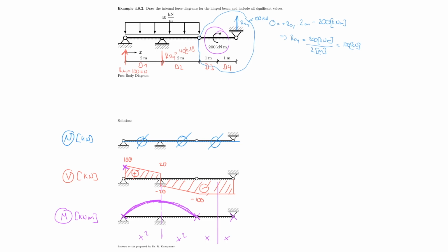So I'm going to try to use a ruler. And now I need to be very careful, because yes, it goes down to that point, and yes, I have to end up at 0 here at x equals 6 meters, but something has to happen in between, because you can argue this 2 ways. Number one, you have this concentrated moment there. But also number two, we have still a negative slope.